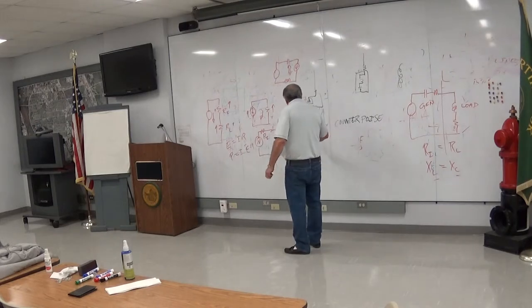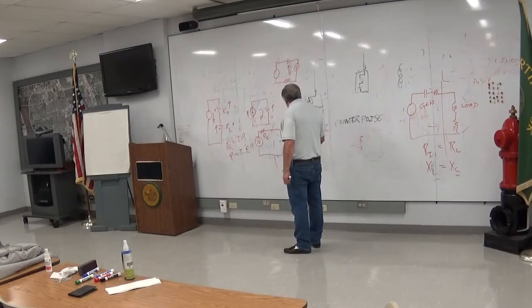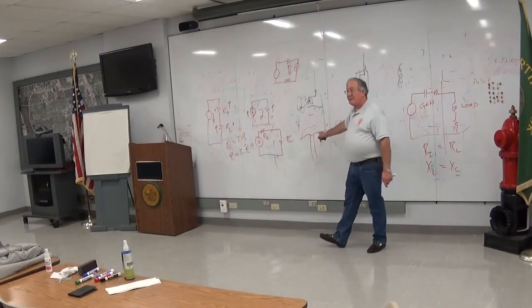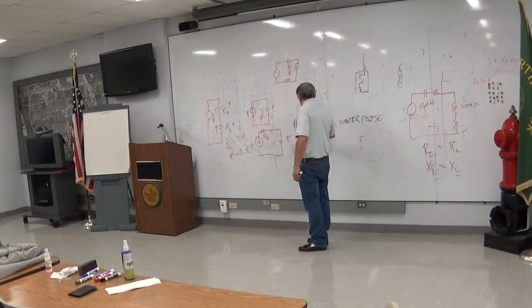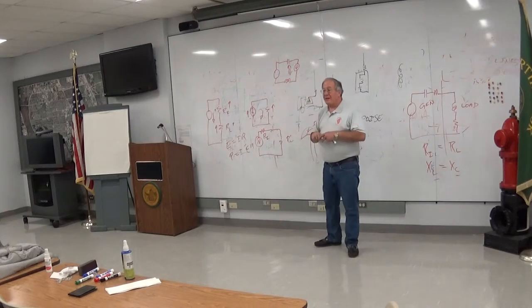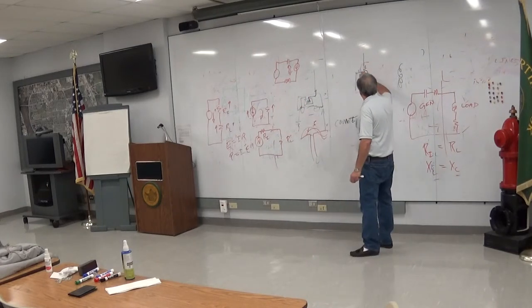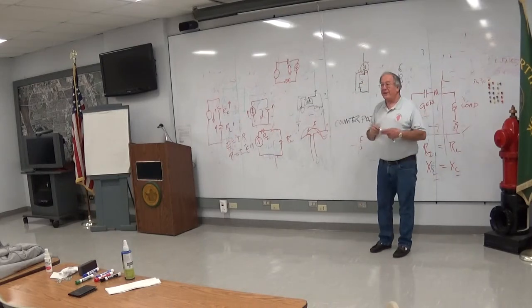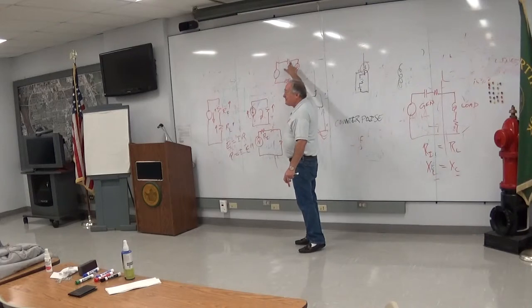The only way to easily understand that is you're going to have a traveling wave instead of a standing wave. It's going to be more like this. And if it's too short, it's going to have the current leading the voltage. And that's going to be characteristically what a capacitor does. So what you want to do is offset it by putting an inductor there to do exactly what this guy did to offset this guy.